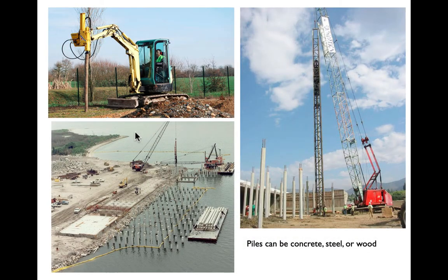So here's a piling operation at a couple of different scales. This is a pile driver at a sort of residential scale. And you can imagine that hammer driving that timber pile in, and eventually our intuition tells us it's not going to go any further. And that's not because it's hitting strong soil below it. It's because the fluid nature of the soil around it is providing enough friction to resist the vertical load that we're putting on it.